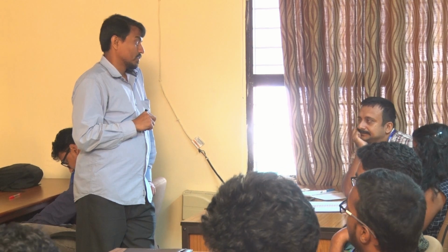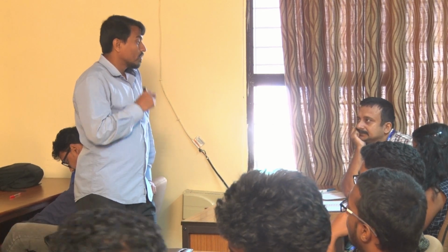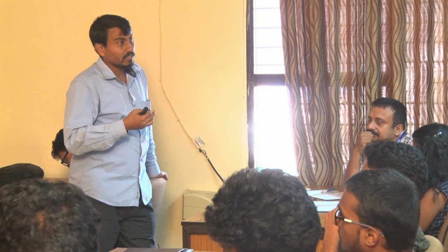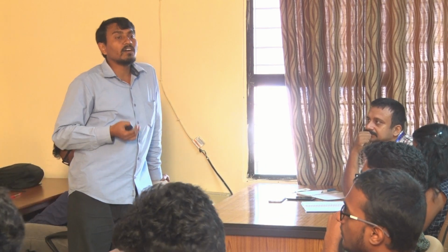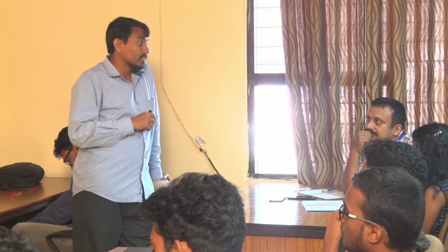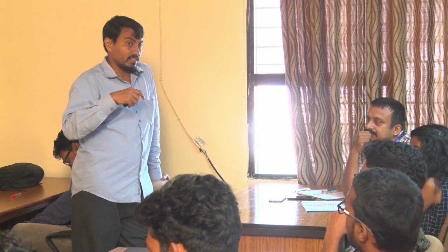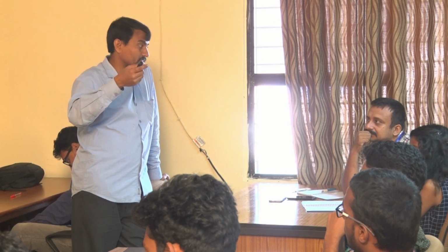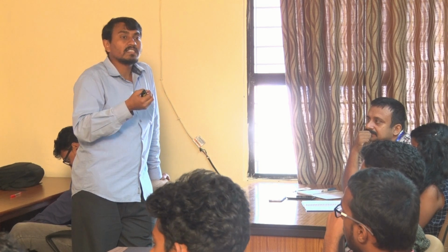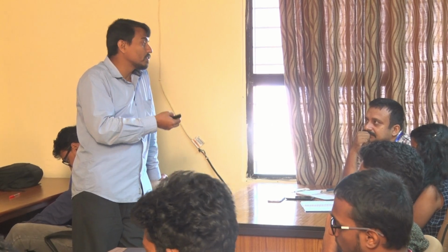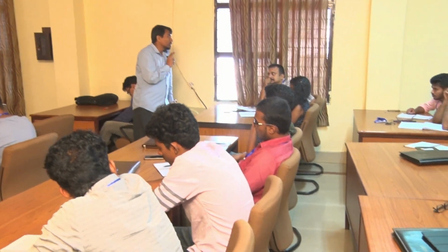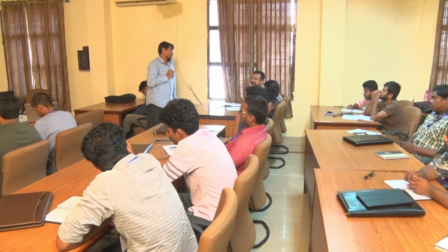So you have to assess all the parameters first. But second, even after getting all the parameters and coming out with some RMR value, they say calibrate with the old data set, whether this particular site's data set is useful or not. So two things we need to keep in mind.